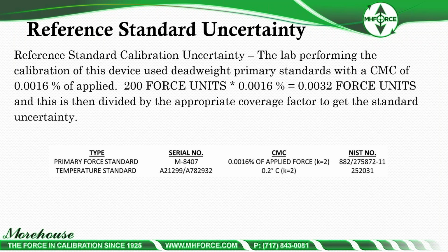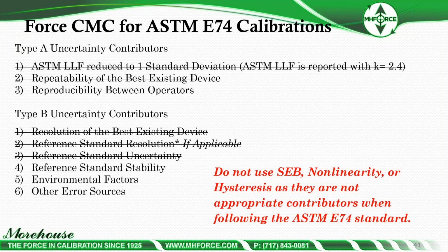The lab performing the calibration with the device using deadweight primary standards with a CMC of 0.0016 applied. So there we get 0.0016, 200 force units. We're going to enter 0.0032, and then we're going to divide by the appropriate coverage factor. In this case, it's K equals 2.